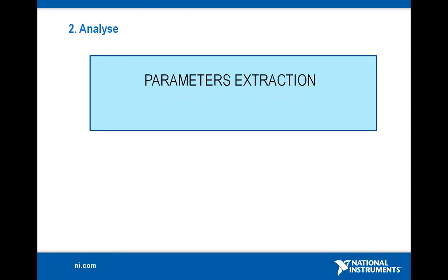In the analysis phase, the most important phase was parameter extraction. Parameters like MFCC, delta, and acceleration were extracted from the data. MFCC stands for Mel Frequency Cepstrum Coefficients. Humans have high frequency resolution at low frequencies and low frequency resolution at high frequencies. MFCC is the cosine transform of the log of Mel spectrum coefficients, where the Mel spectrum coefficients are equal to windowing coefficients multiplied into power spectrum coefficients, where windowing coefficients account for the non-linear frequency resolution of the human ear.